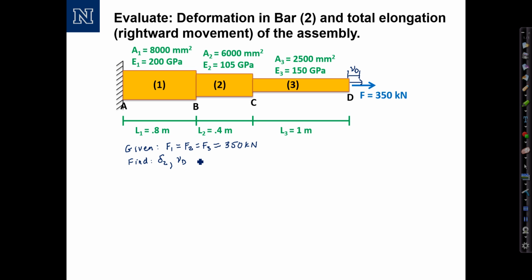We expect them to be small quantities. We want to calculate these deflections in millimeters. Considering the units we are given for this problem, force in kilonewtons, elastic modulus in gigapascals, areas in millimeters squared, we can work without having to do any conversion, with kilonewtons, millimeters, and gigapascals.